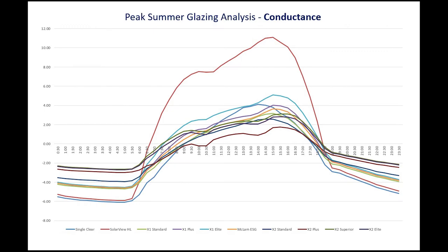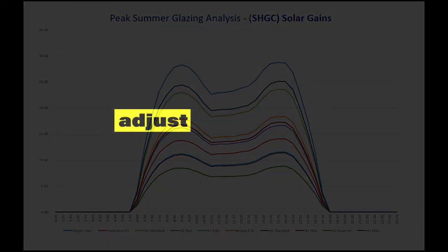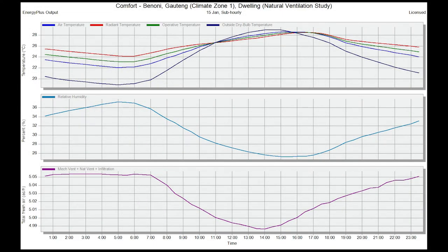We can further run a glazing analysis on an endless plethora of various glass specifications to help optimize what glazing specification might bring the best performance to any building anywhere in terms of minimized energy consumption, maximized thermal comfort, and return on investment, comparing capital cost expenditure against simulated return on performance. We can adjust the specification of any individual element of the building envelope or internal services to analyze and review any benefits thereof in refining design specifications. We can also specifically simulate either natural ventilation studies or various forms of air conditioning and mechanical ventilation to suit the aspiration of any building design and use.